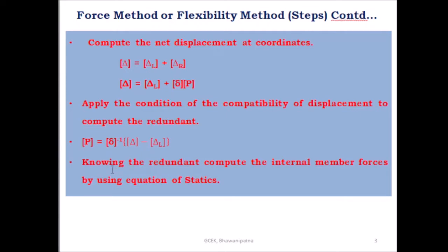Then after knowing the redundants, compute the internal member forces by using the equations of statics. So these are the different steps you have to remember to solve any continuous beam using the flexibility matrix method.